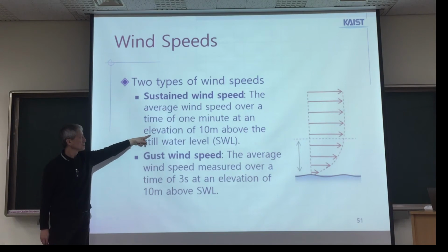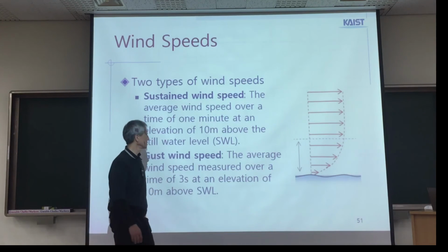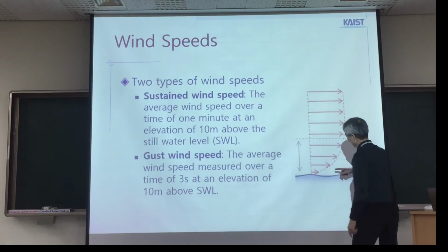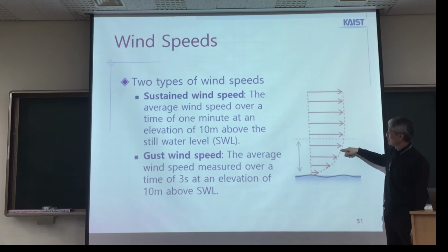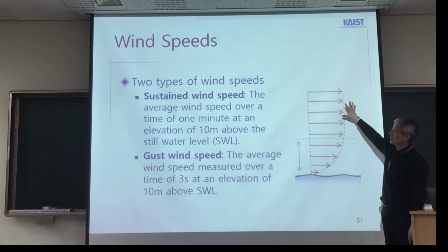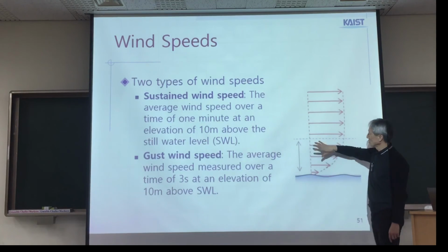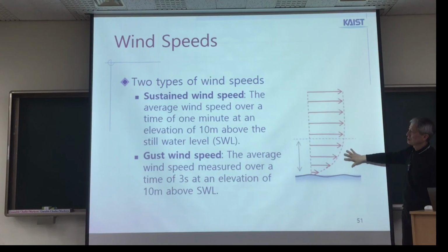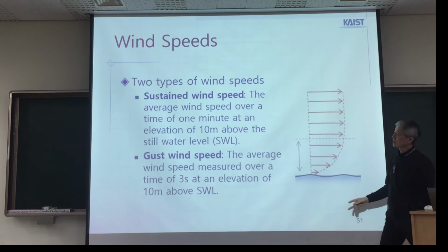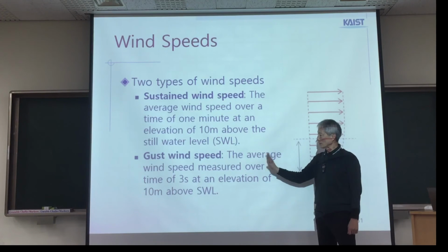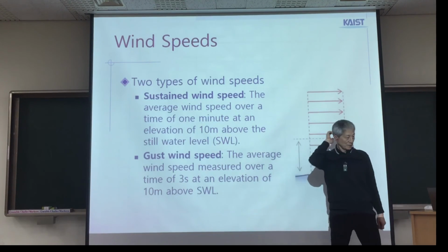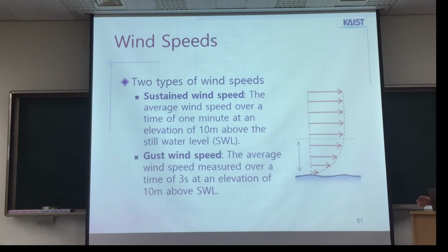And also elevation is important. Where you measure matters, because depending on the measurement point, the wind speed is different. Right? So 10 meters, probably depending on the boundary layer size or depth. And also there is something like gust wind, fluctuating wind, high speed, fluctuating winds coming.